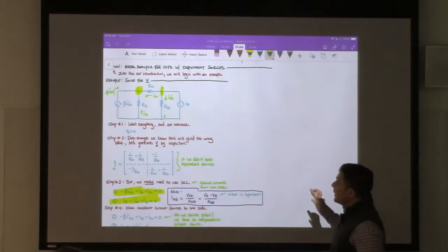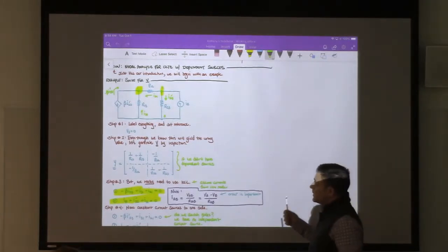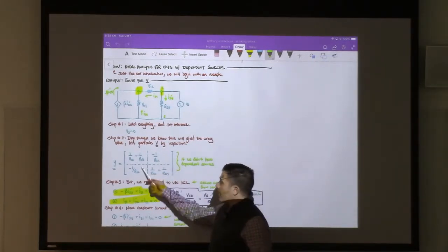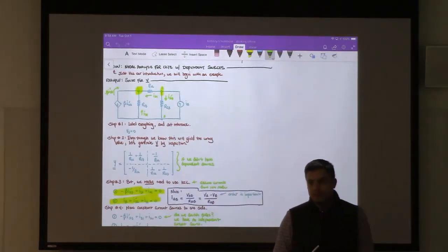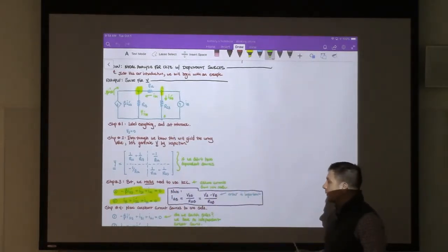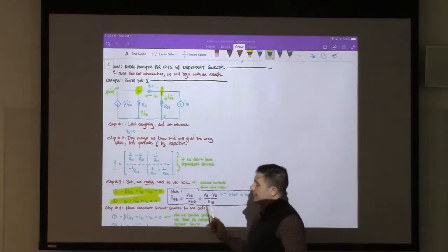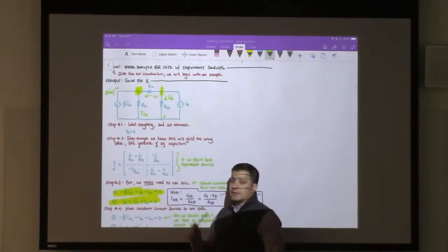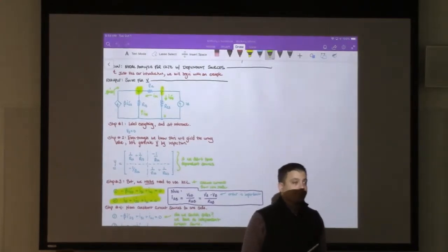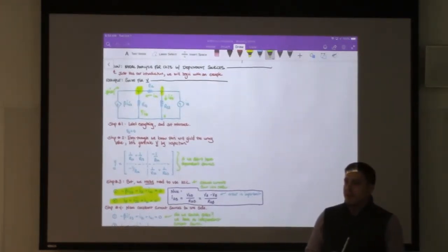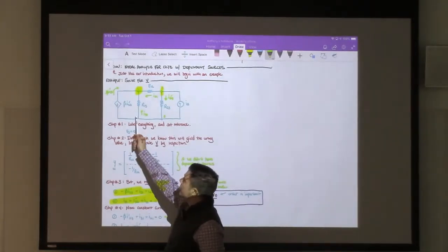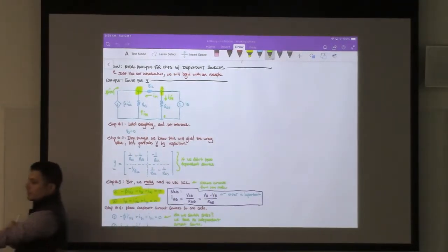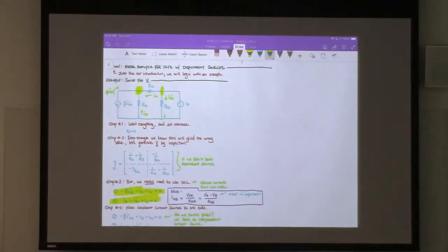When we have a dependent source, it changes the problem a little bit. It messes up our ability to use inspection. What it specifically does, at least in this case, is it breaks the symmetry of the admittance matrix and changes this element that's connected to node number 1.